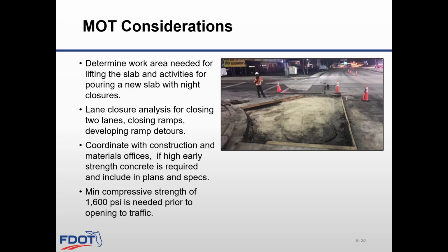Coordinate with construction and materials offices if high early strength concrete is required and include in the plans and specs. The minimum compressive strength of 1600 psi is needed prior to opening to traffic.